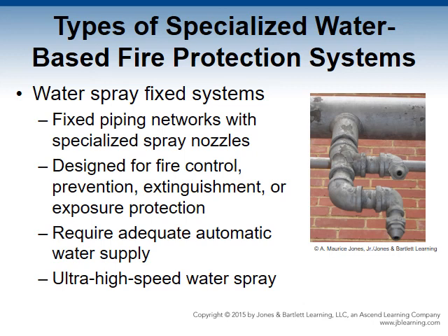Automatic nozzles use the same basic technology as automatic sprinkler heads. Open nozzles have no heat-sensitive elements. They are available in high and low velocity. Plugs or blow-off caps may be used to keep water ready within the piping at all times. There are various types of steel and copper tubes that have been approved for use with these systems, such as galvanized and stainless steel.